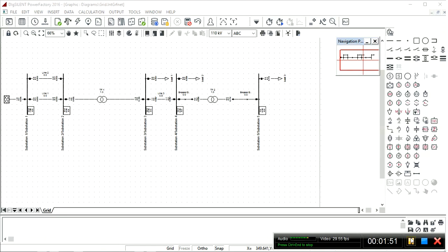Well, what is the difference between these two methods of connecting the transformer? In this method, we put a dummy node in between the transformer and the bus bar. This method does not. By inducing a fault on the dummy node, we can simulate an internal fault on the transformer, simply because the dummy node represents the transformer bushing.